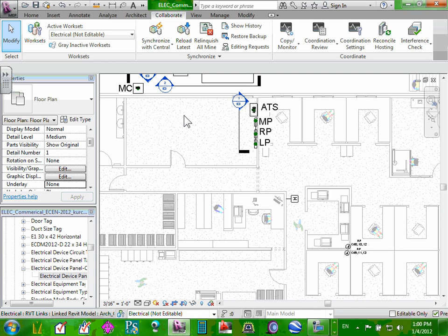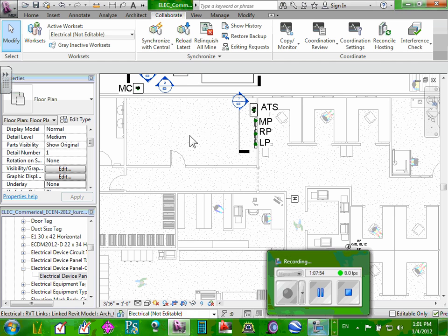The power connection is only for the island. And you know, Nick, why? Because the island doesn't have a wall. It's cheaper, guys, to put the receptacles in the wall versus putting it in the floor as a J-box. That's why, if you have a cubicle that's attached to the wall, and you have a wall here, put the equipment in the wall. Okay, that's all I have. We synchronized. Everybody synchronized? Thank you, guys.